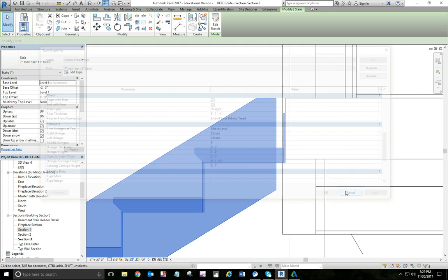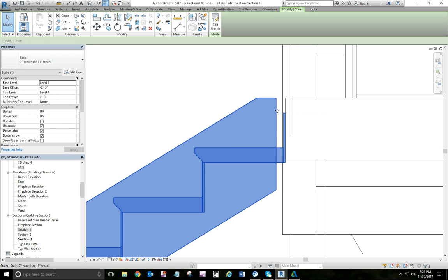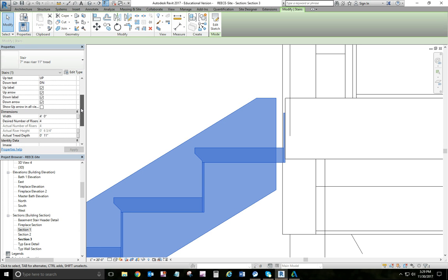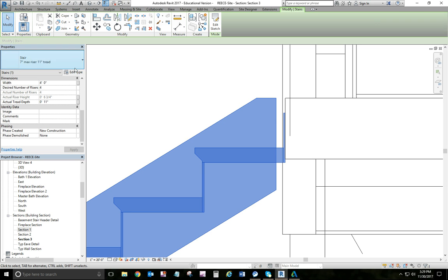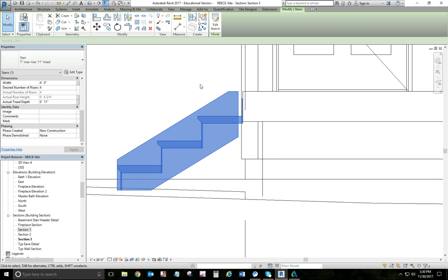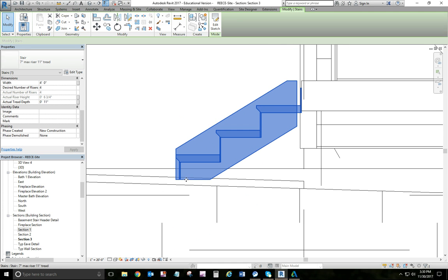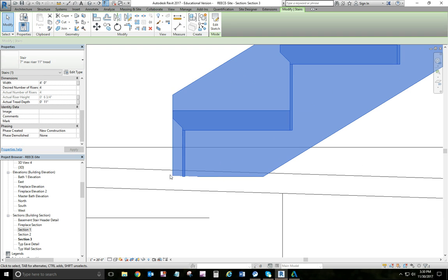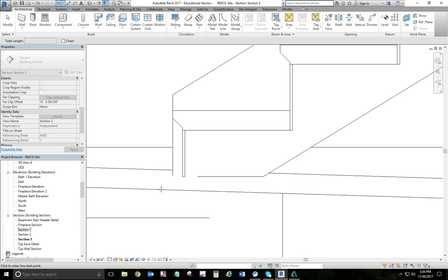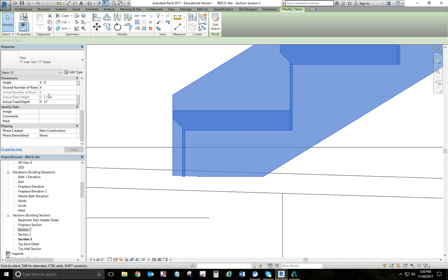Okay, so somewhere it is in my type. Anyway, I got to find a place where you edit the offset of the stringer there. Okay, and then you may have to adjust the height of your stair where the start level is once we get down here and we see where it's at. 49, so we'll say 3/4 of an inch. Okay.